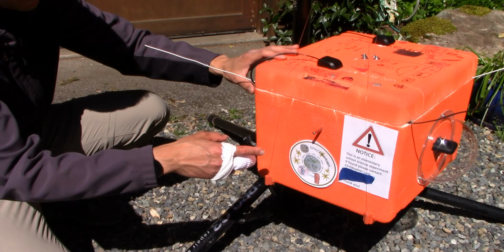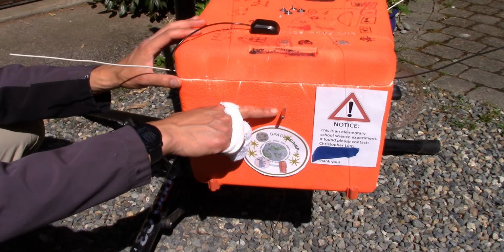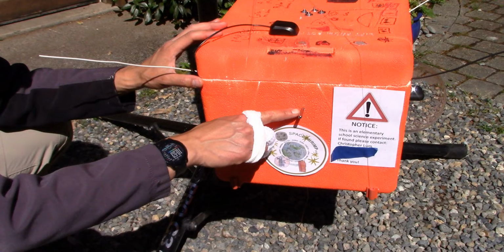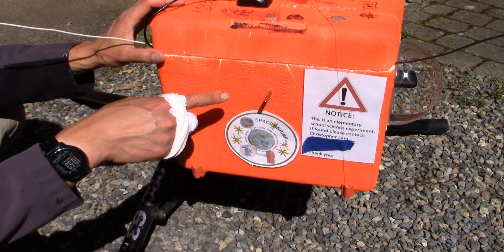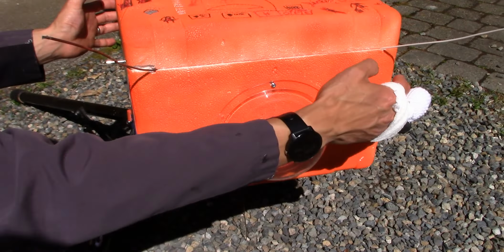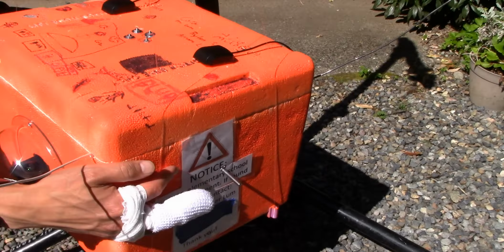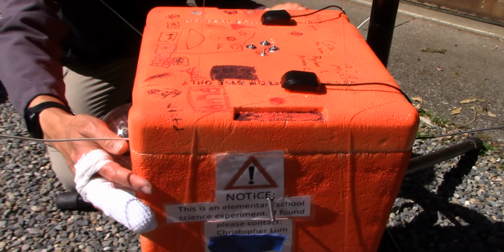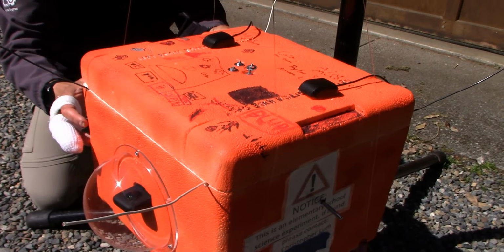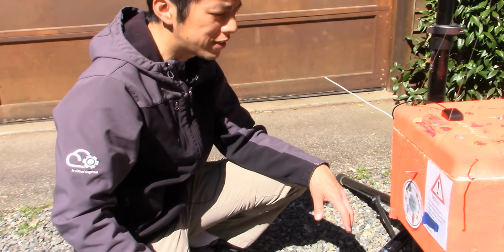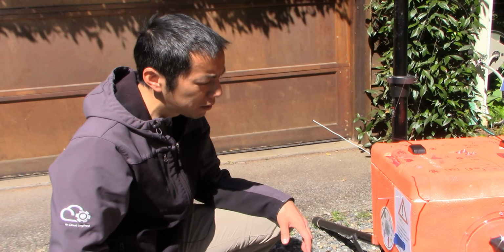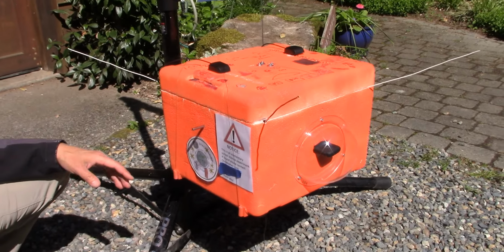On this side of the exterior, you can see we actually have a temperature sensor, kind of a thermocouple that is sticking out to get exterior temperature. And we actually have two of those. So we have one on this side and then one on the opposite side as well. So in the name of aerospace redundancy, we're going to collect that signal using two separate, completely independent sensors and data acquisition systems. Again, for redundancy.